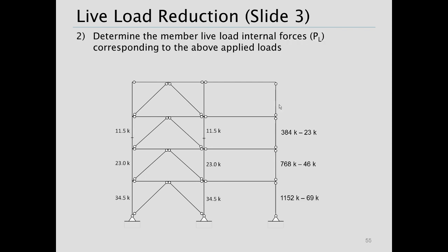All right, so once we've done that calculation here, we'll do a live load takedown in our columns, just tally everything up as we go down the building. What's the axial force supported by each of the members.